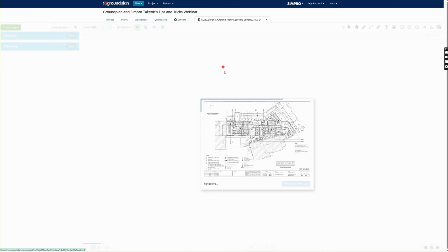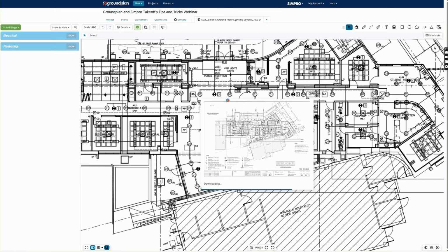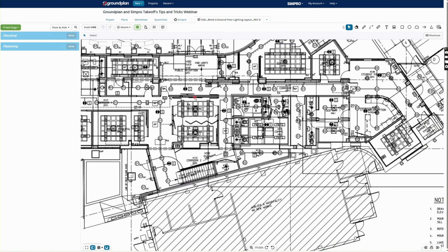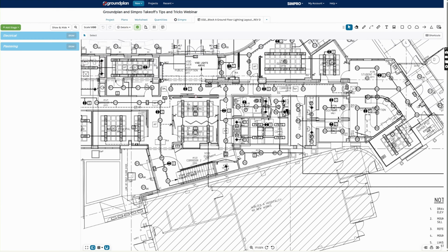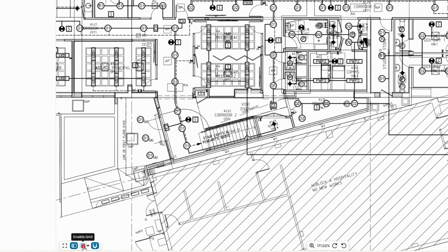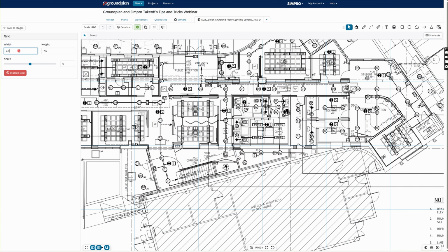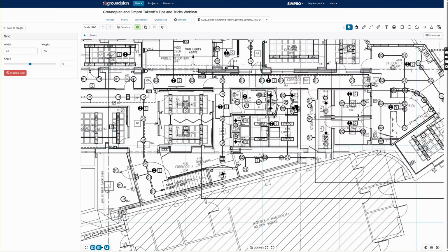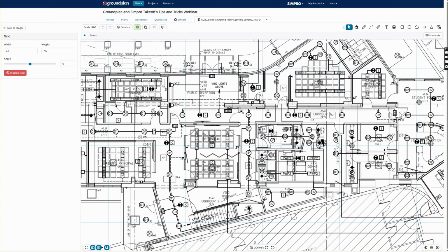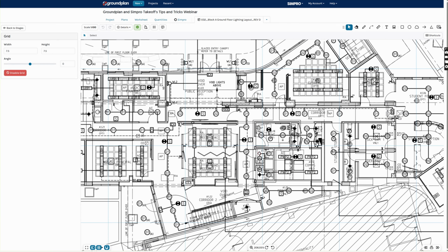Now, James, you want to measure a circle radius for a smoke detector of 7.5. So you're taking my grid to all new levels here, James. So I would personally click Enable Grid and then use my little grid settings here. And we reckon it's a 7.5. And this is then giving me my grid boxes that are 7.5 by 7.5.